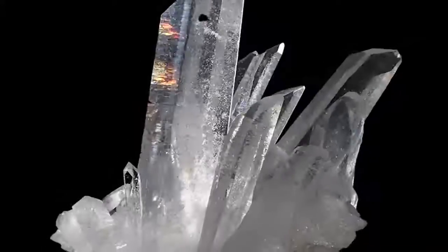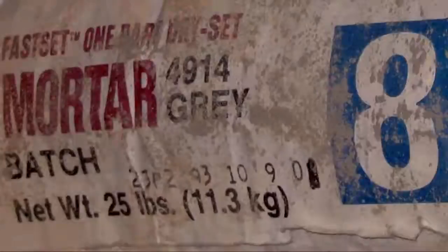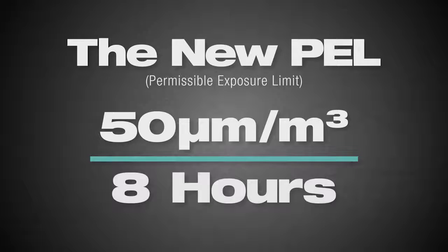Crystalline silica is generally found in concrete, brick, and stone products, as well as man-made stone and other masonry materials. This means the rule covers a pretty large group of trades, from roadwork to decorative concrete to countertop installation and more. Due to health issues related to silica dust, OSHA has reduced the permissible exposure level, or PEL, for silica dust, to 50 micrograms per cubic meter on an 8-hour time-weighted average.